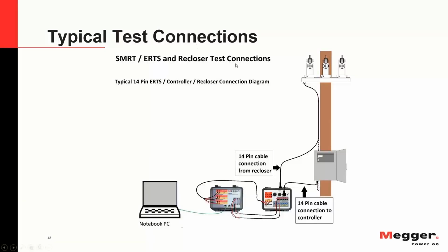Now, that sounded a little bit too abstract, so I'm going to put it a little bit more clearly. You have the mechanism here, and the mechanism has the sensors. The sensors have the CTs and PTs, or resistive sensors, that bring the analog signals into the relay. Okay? Now, if you want the relay to operate, you have to inject those analog signals to the relay.